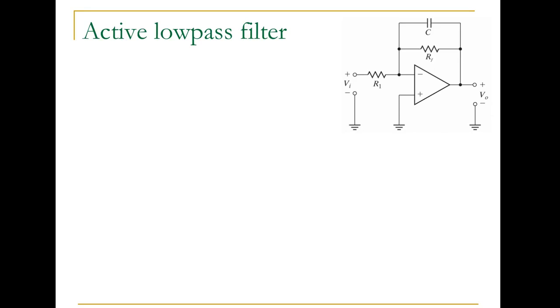Noise will always be present in measurements, and so filtering comes into play. One thing that's helpful for filtering out unwanted signals is knowing the frequency of the desired portion. For example, if we're using a thermocouple to measure temperature changes in a room, we know that the temperature is going to vary slowly. So any high frequency components to our signal we could filter out because those are just unwanted noise and don't really represent the temperature of the room.